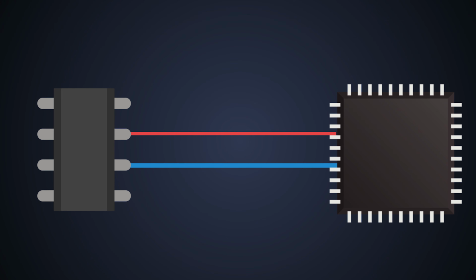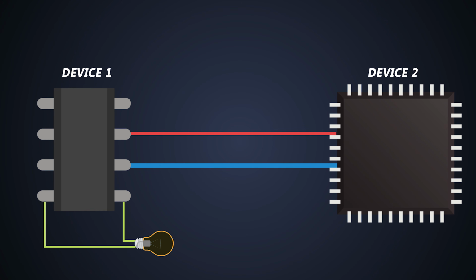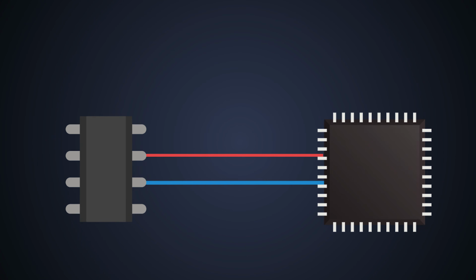For example, we are sending the data from the first device to the second. While sending, we want to execute some parallel operations, say blinking some LEDs. If you use looping method, then the data will be transferred from one device to another, and after that the LEDs will blink because our software is busy monitoring this data. But if you use an interrupt method, the data will be sent and it can blink the LEDs simultaneously for us. And when the data is transferred, it will just generate an interrupt.